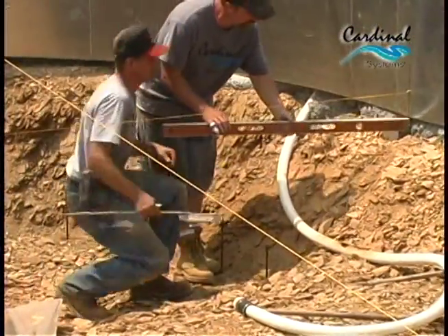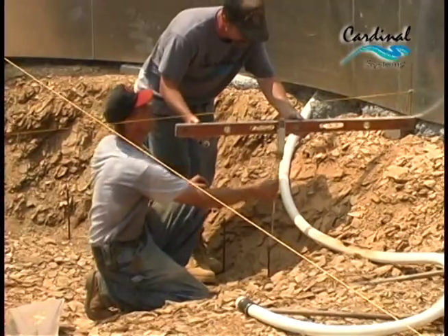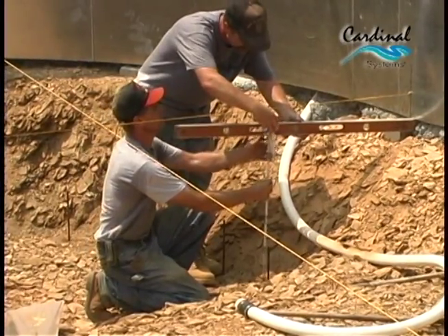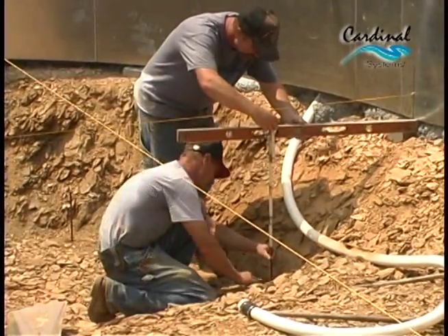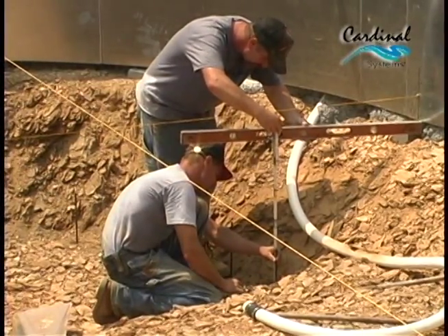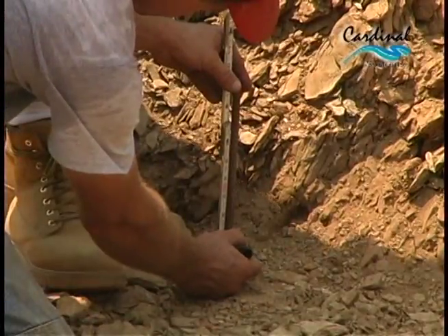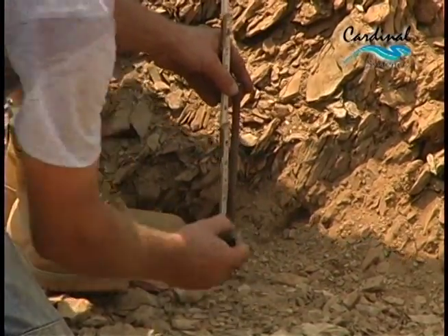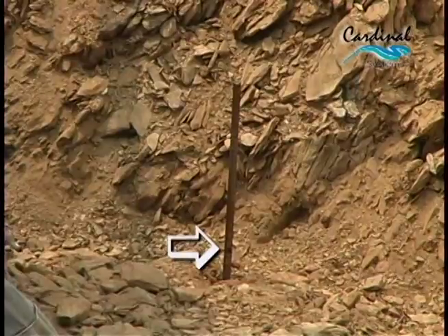Once the entire arc has been laid out with rebar, you'll need to mark a point on the rebar that will serve as the level to which you will float the concrete bottom of the pool. Run a level from the bottom edge of the pool wall over to the rebar and measure down 30 inches. Use a marker to draw a line on the rebar at this point.